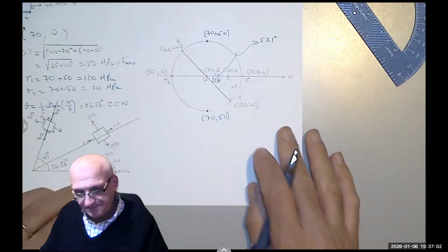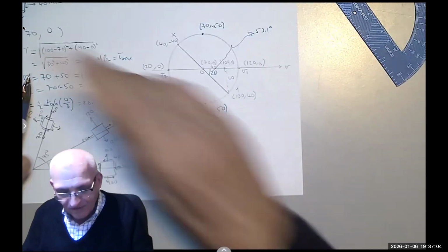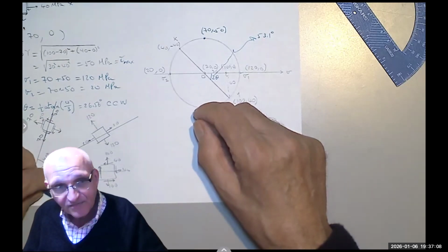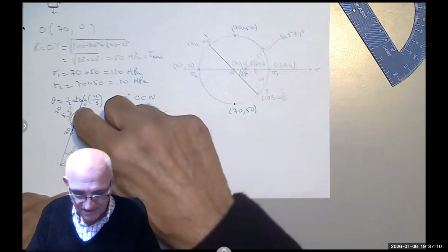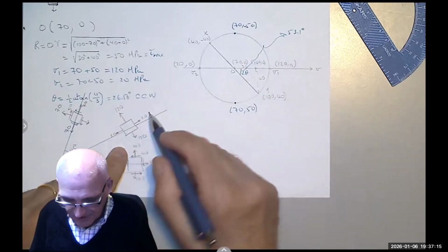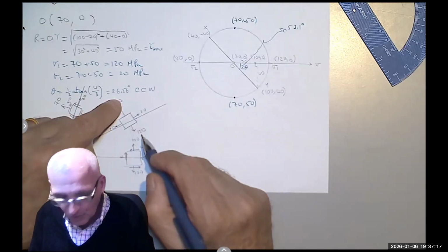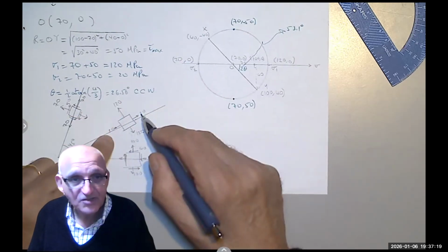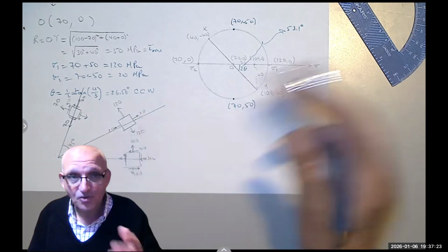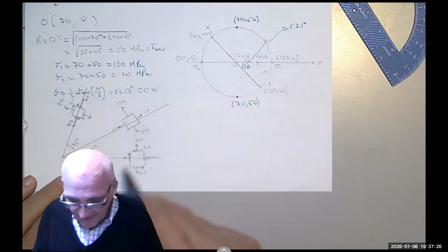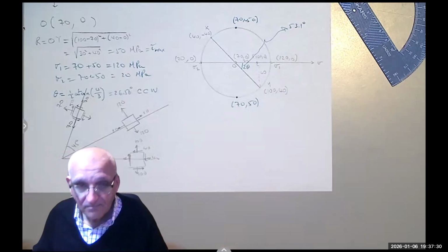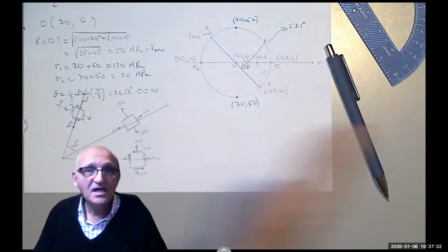70 megapascal. So this is the plane of maximum shear, or the normal to it is also plane of shear, but these arrows would reverse. And these are the principal axes, and the maximum normal is 120, the minimum normal is 20, both are tensile. So this part is not subject to compression at all. And the maximum shear is 50. Okay, and that's basically how we draw it.